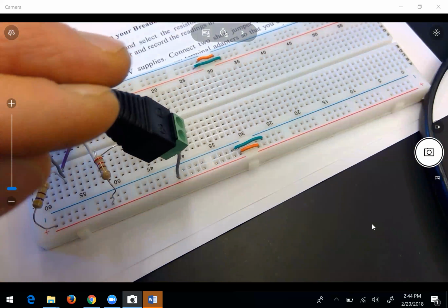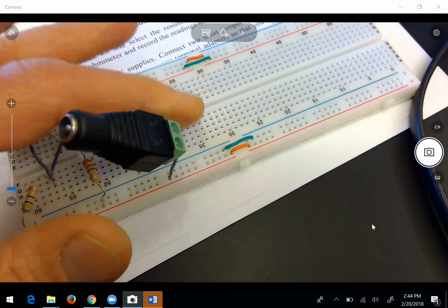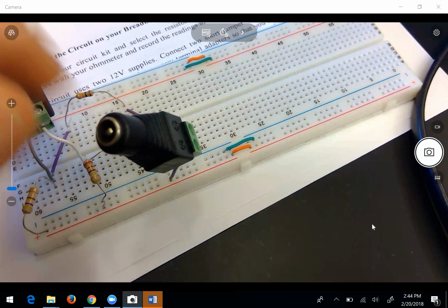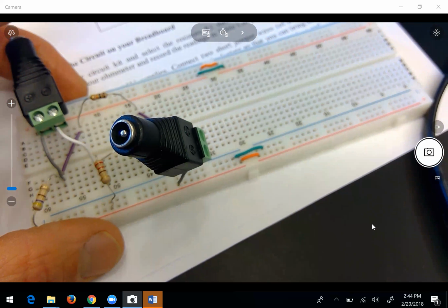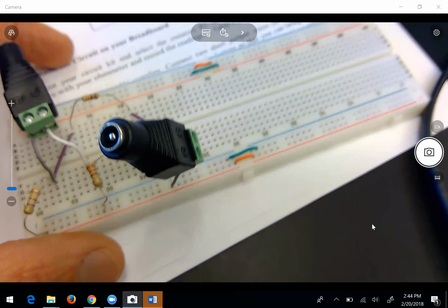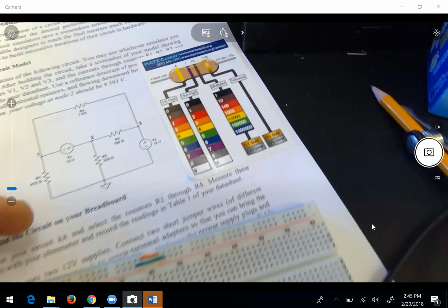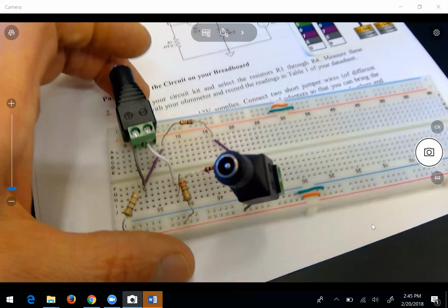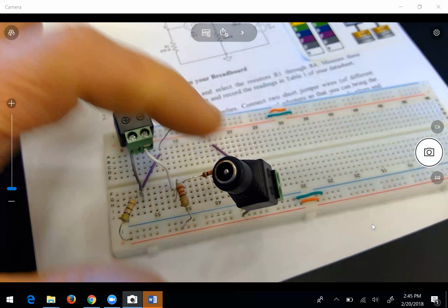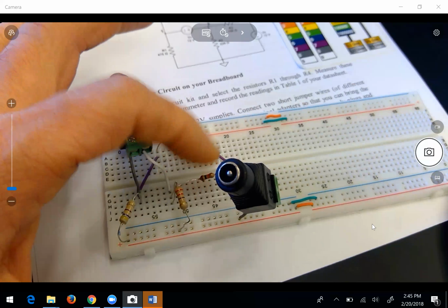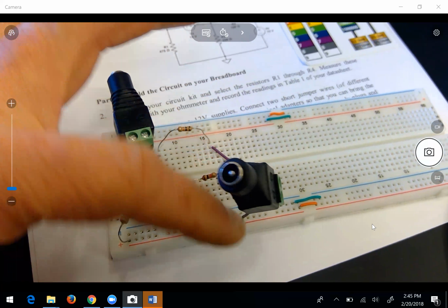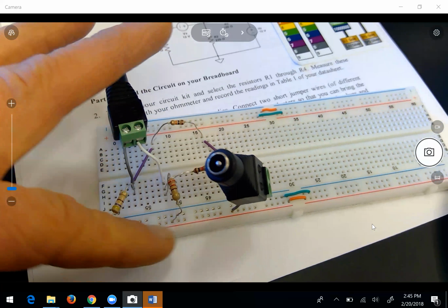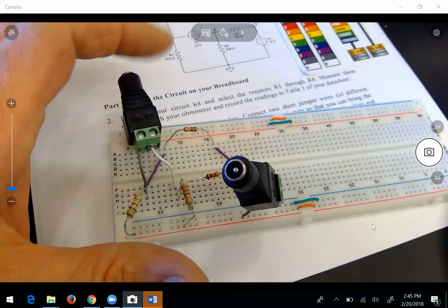This power supply is also wired backwards. Notice the low potential side is going to node 3, which should be the high potential side. Brown, black, brown, because you want to take 10 and multiply it by 10 to get 100. Okay, that's where I was confused. So you're going to switch those polarities and colors, and then switch that resistor to the 100 ohm resistor. This is a reference node, so that looks good, and those are connected across, so otherwise it looks good. About 3 changes to make.